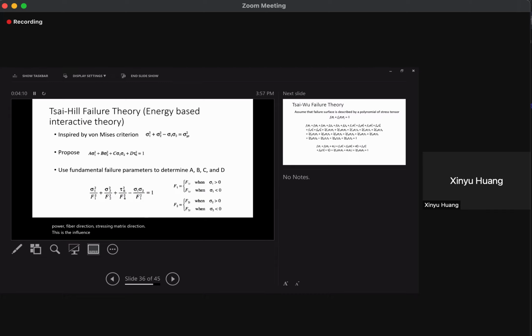So basically this combination. One of the ad hoc theories proposed that if you combine these stresses like this, you make them equal to 1, let that capture the failure boundary, and then you just fit these parameters. You use the experimental data to find what A, B, C, and D are. That's the theory assumption.